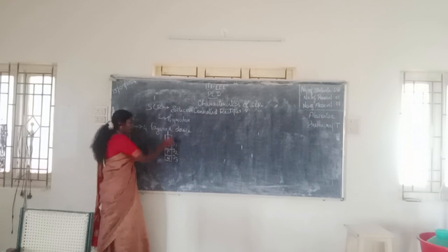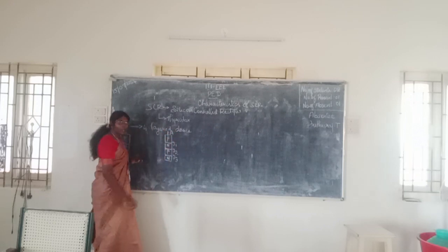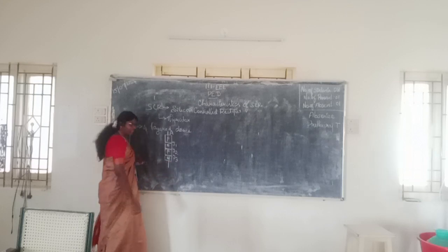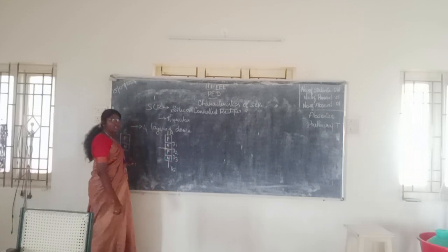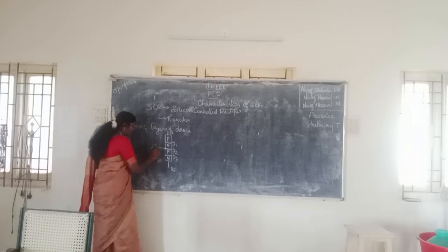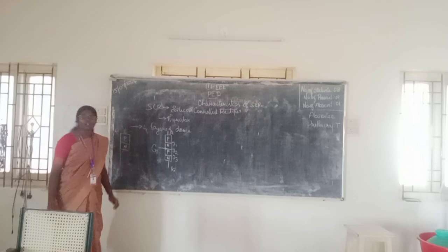Terminals: for this P we will have the anode as a terminal, and this N-type semiconductor will have the cathode as a terminal, and the middle junction J2 is going to have a gate as a terminal. So this will be the same in the construction part.